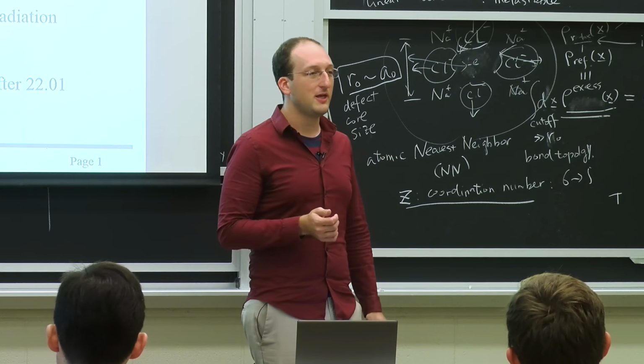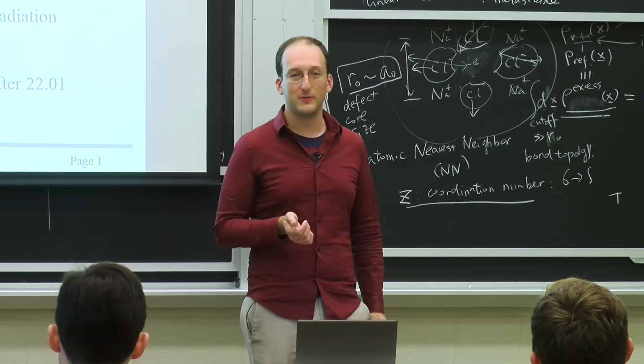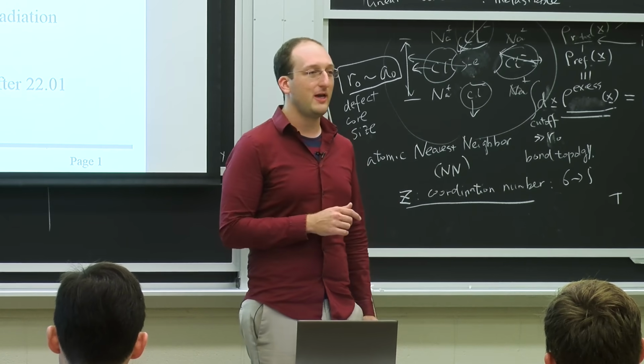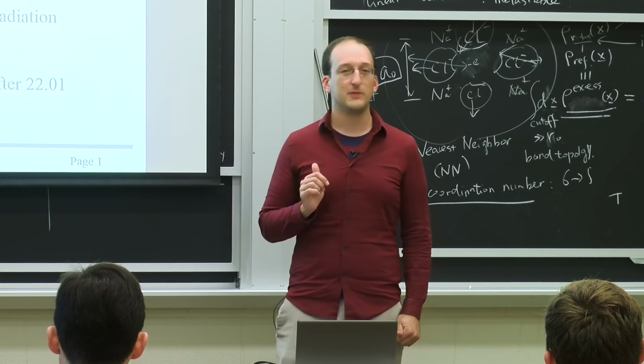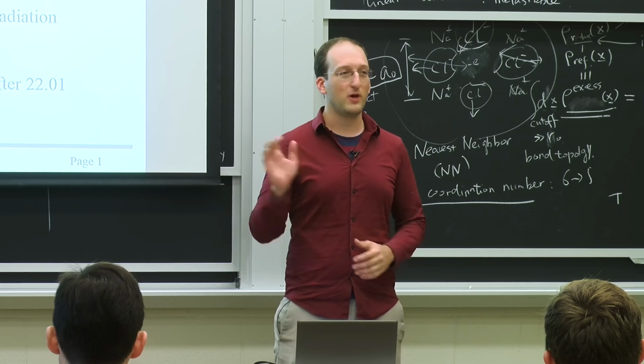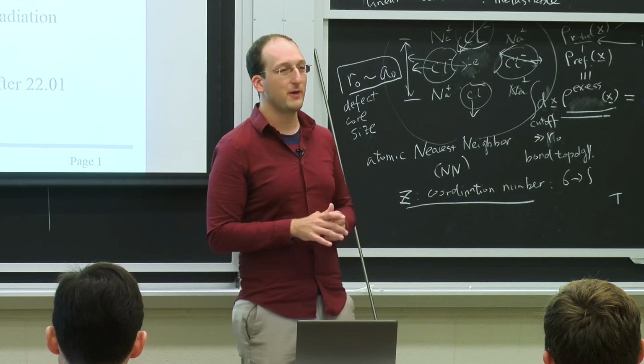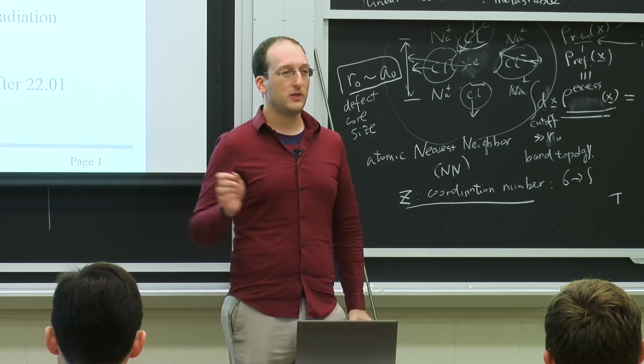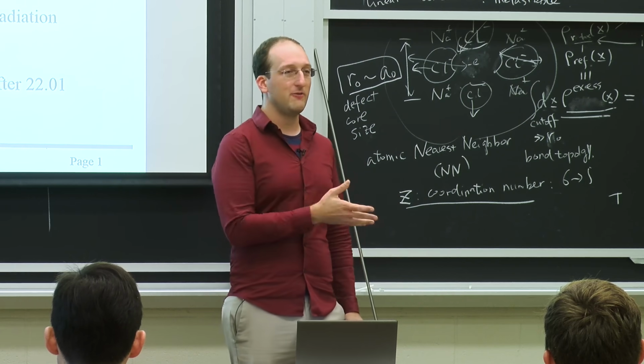And for recitation today, since we haven't gone over any technical material, we're going to be heading to my lab to demonstrate one of these things, a sputter coater, which is a controlled system for radiation damage, which applies one material to the other via the process of sputtering, or actual nuclear or ionic collisions that blast material, in this case gold, onto whatever you want to coat, which in this case is a pile of pocket change. So we're going to make some gold change today.